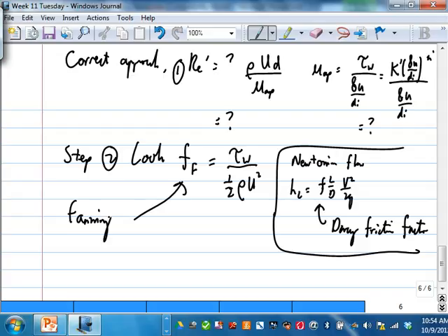The reason why we have two is because this chapter was taught by mechanical engineers, and this chapter was taught by chemical engineers. Alright, so just to confuse you there. Actually, both conventions are correct. There are two conventions around. This is the Fanning friction factor, that's the Darcy friction factor. So Newtonian flow, pipe flow, Moody chart, etc. use this one. This week in our tutorial we'll still use this one, because this week we're doing pumps and Newtonian flow. Next week, when you do non-Newtonian flow, use that one.